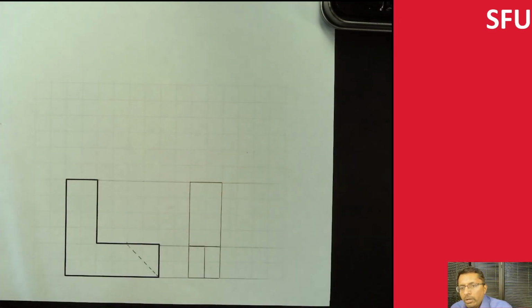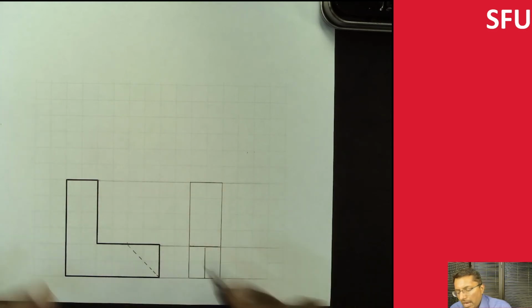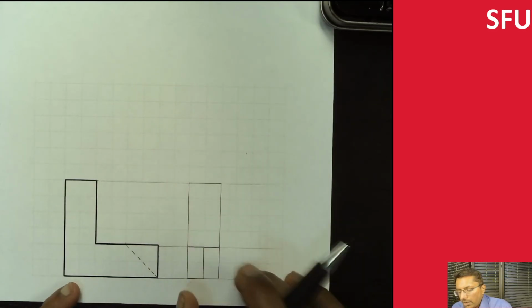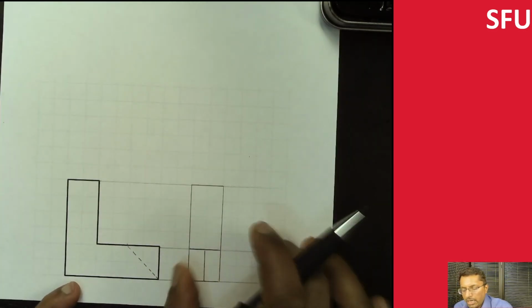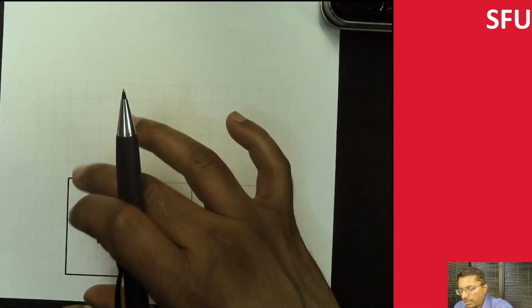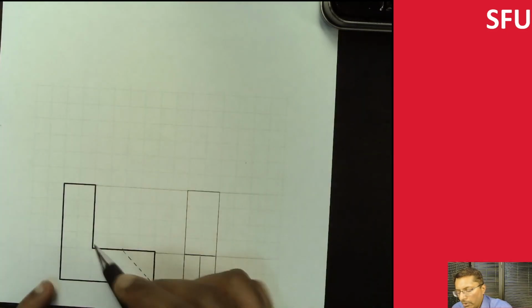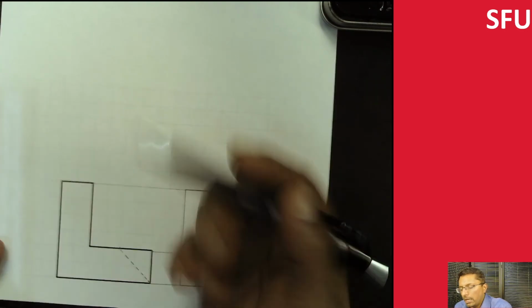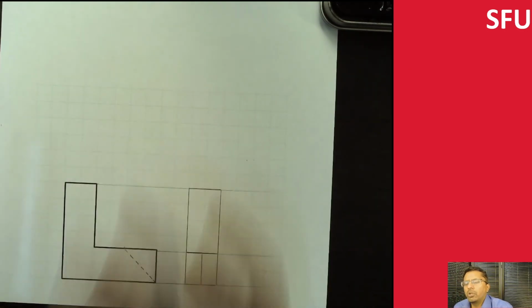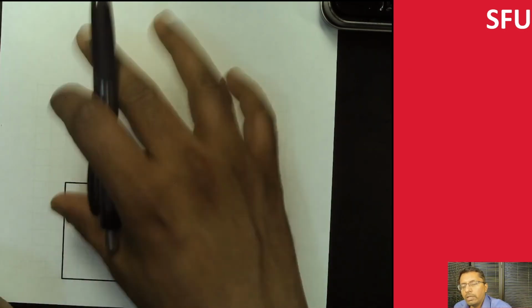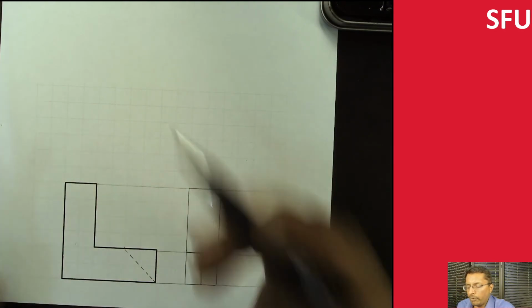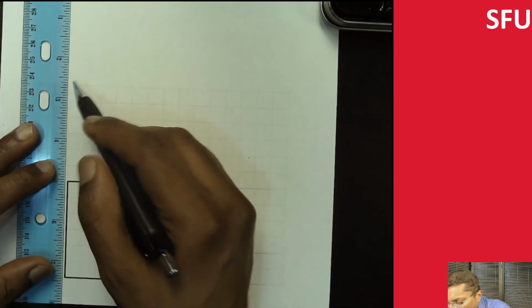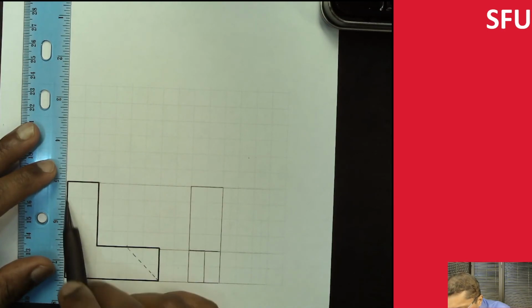So what you're going to be doing now is use the fact that the right side view and the top view are sharing the depth information, and the front view and the top view are going to be sharing the length information to actually construct a top view. So to put it in another way, the size of the top view isn't completely independent. So let's see how we can actually do that.